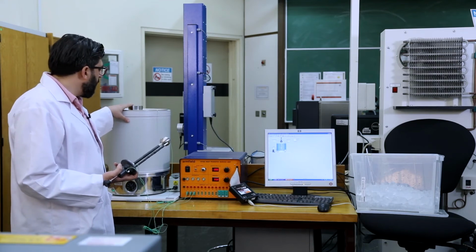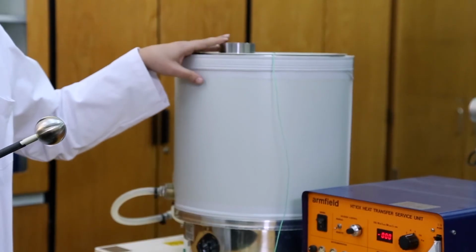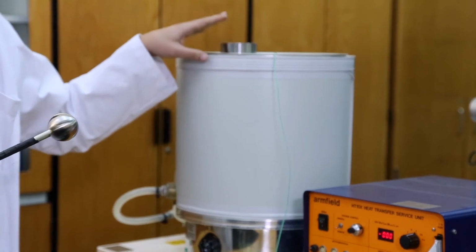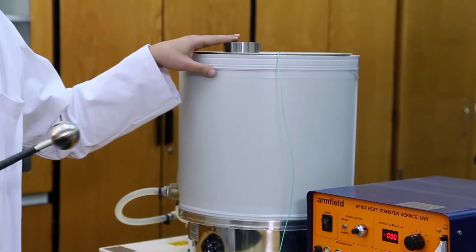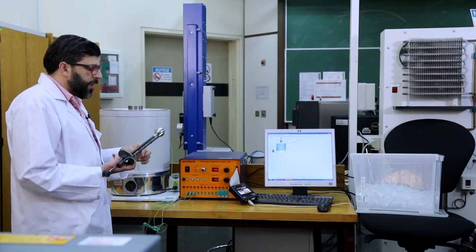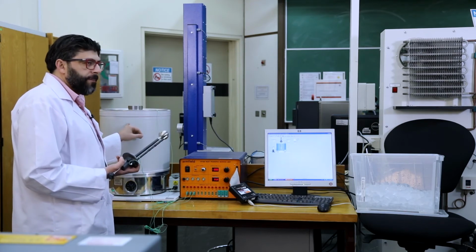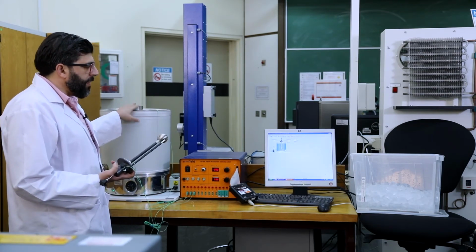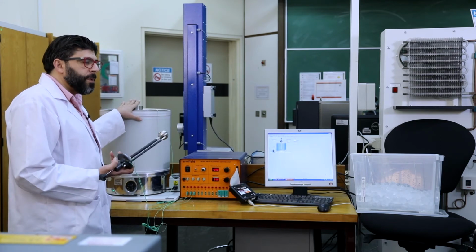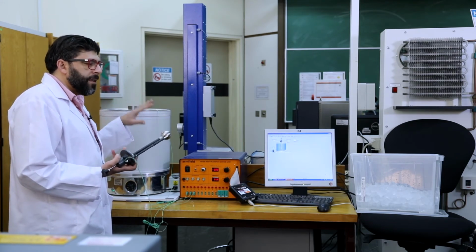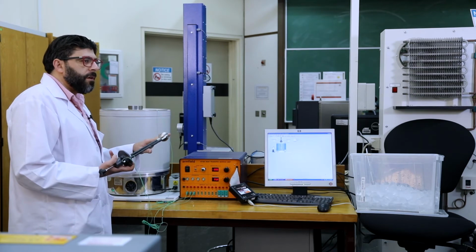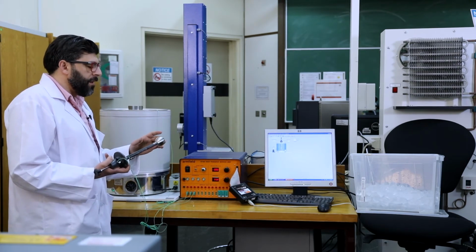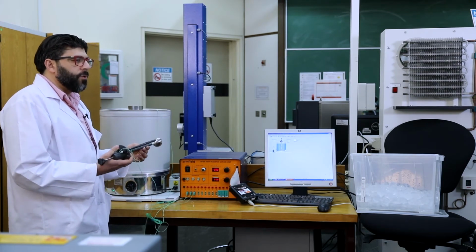So this bath water has a temperature around 55 Celsius. And once we put it in, we will measure the change in temperature per time. This will be the first experiment, until we reach steady state, so no more increase, and the shape almost reaches the surrounding temperature.